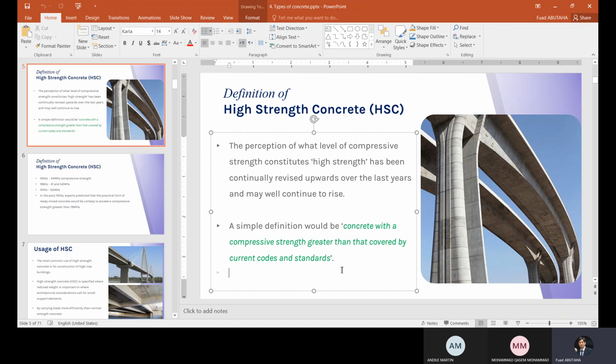You know that coarse aggregate comes in a range: the minimum particle size is 4.75 millimeters, and it can go up to 22 millimeters, so the maximum size range is between 4.75 up to 14 millimeters, or 4.75 up to 19 millimeters, or you can use 4.75 up to 22 millimeter coarse aggregates.